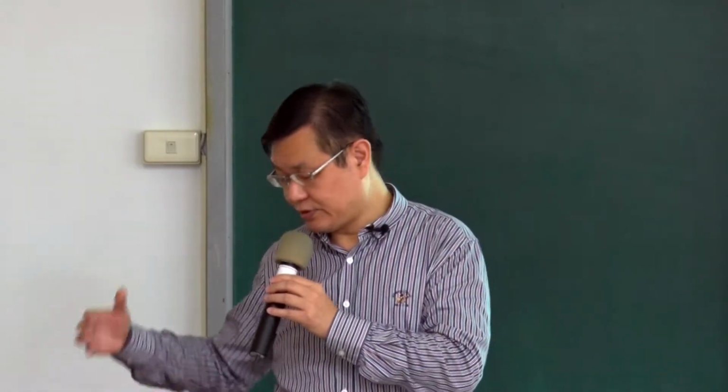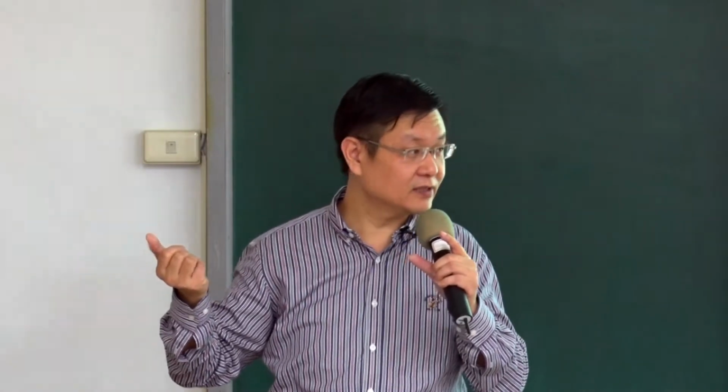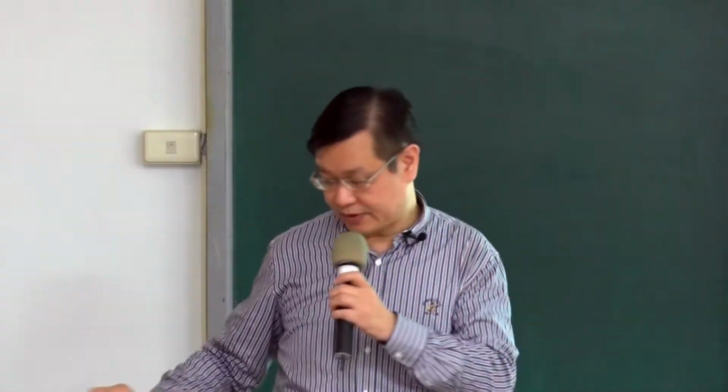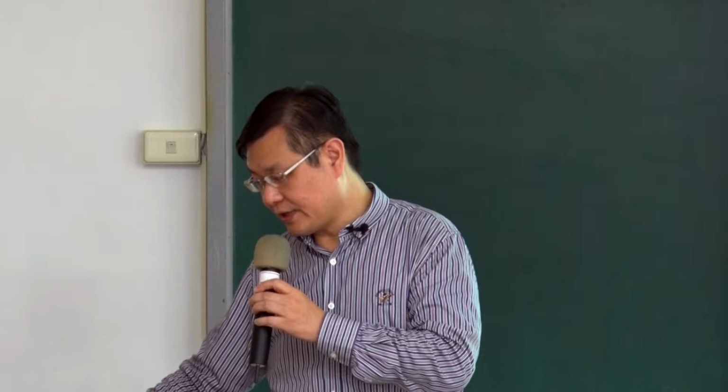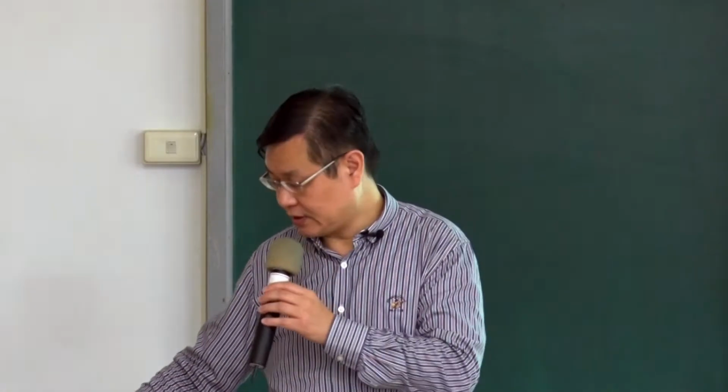So now you know how to do this. I think the mass is easy to count. You just calculate the area and the thickness, and you get the volume, then multiply by the density. You get the weight or the mass of the system. For the spring, you can consider the cantilever deformation like this. So this is the spring constant.